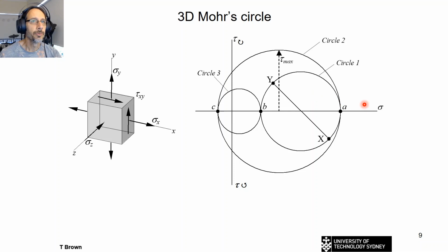All right, so here we have the Mohr's circle. If we start with our normal way of doing things that we've done last week, so this is the revision of last week's work, we have our stress pair here: normal stress in the X direction, and a shear stress. That will be plotted down here. The shear stress is going anti-clockwise, so it will be down here.